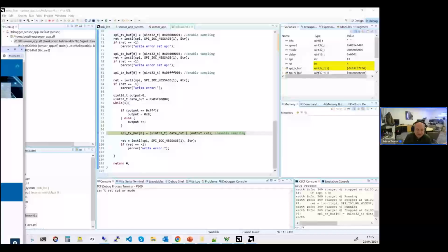So where did I specify the correct PMOD port? That was when I did my pin out. When I did the pin allocation in Vivado with the XDC file, I didn't show it in this lab, but I opened the schematics for the board that I was on, traced the PMOD signals through to the FPGA pins, and then added those in there.